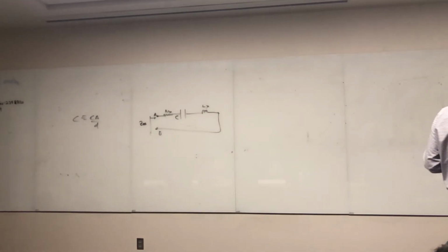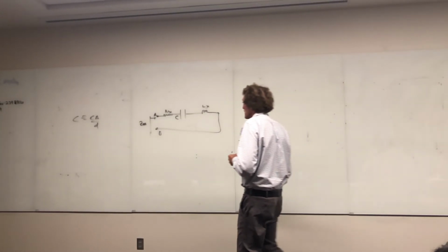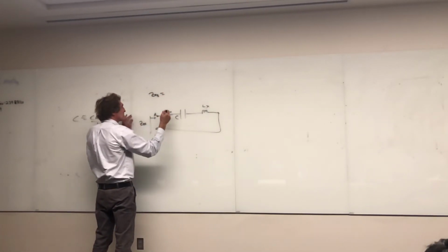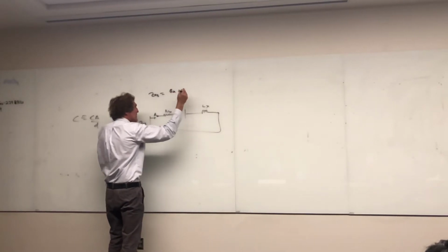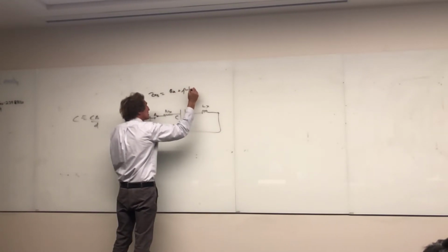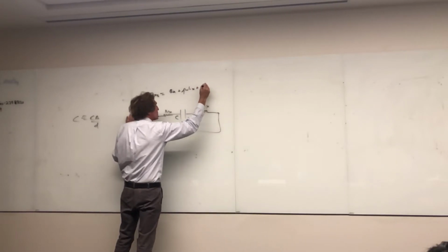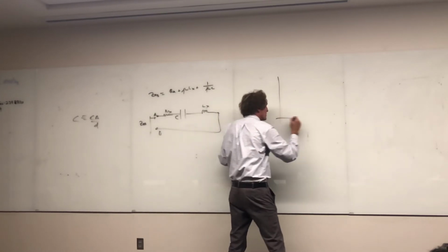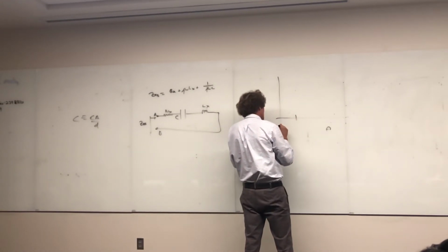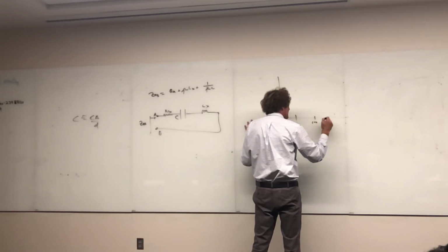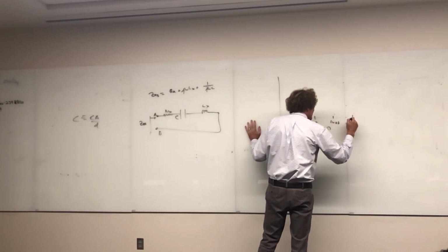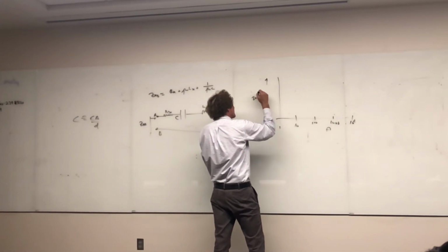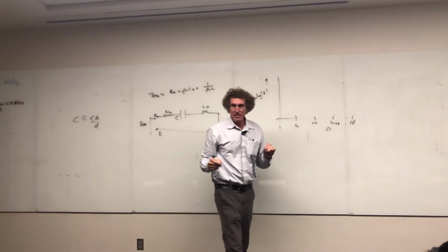But if you look at this in the frequency domain, the impedance of this is what? Well, ZAB here is just equal to Rx plus j omega L, plus 1 over j omega C. And if you look at this versus frequency, and this would be logarithmic, so 1, 10, 100, 1,000, 10 to the 4, 10,000, and then here, 20 times the log of the magnitude of Z. This is the neat thing.